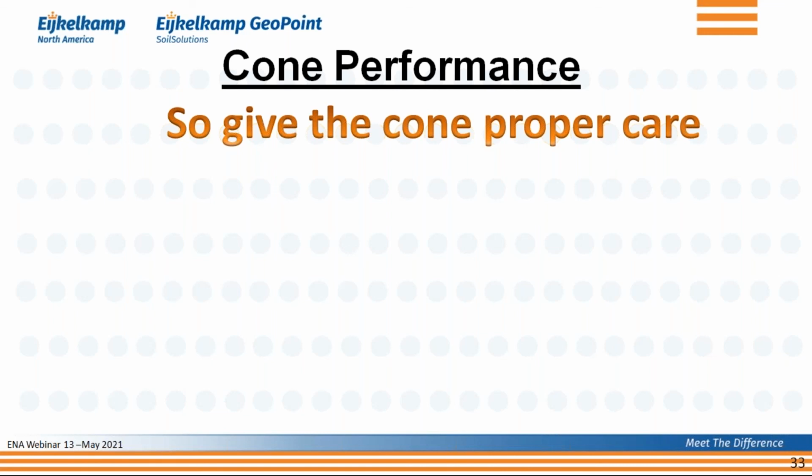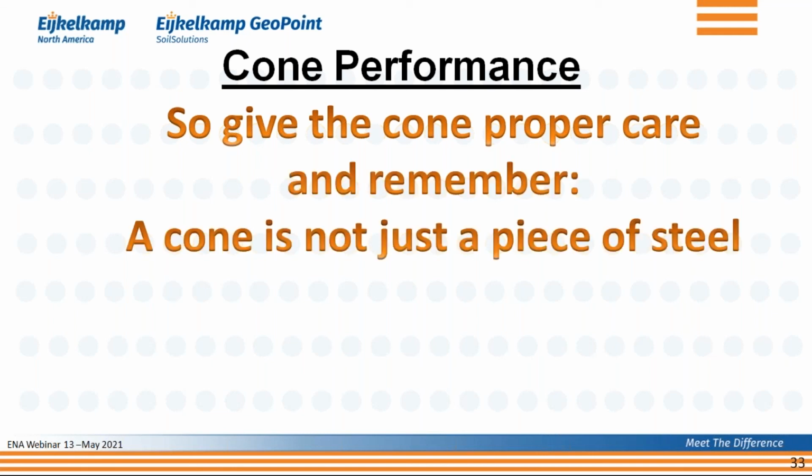But a cone, if you don't size the pressure sensors or the load cells appropriately, you can easily damage the cone. It's important to remember, a cone is not just a piece of steel. It is a very sensitive instrument that can give you very good data, very accurate data, as long as you take care of the cone. And that's why I started out with give the cone proper care.